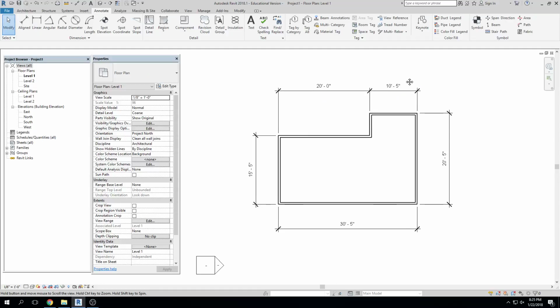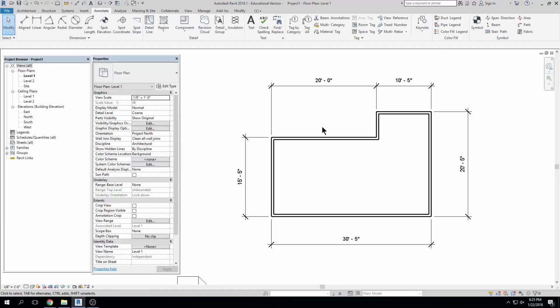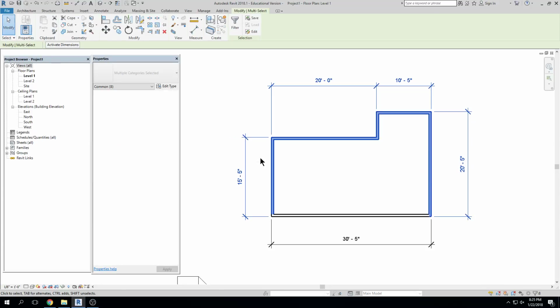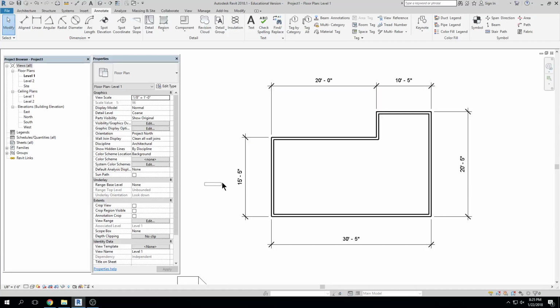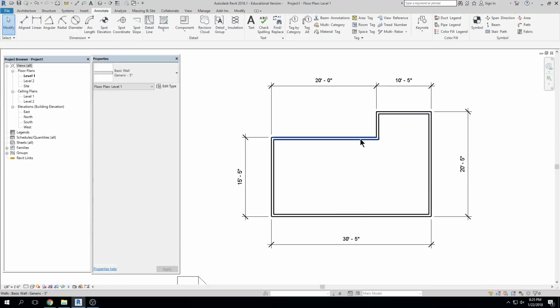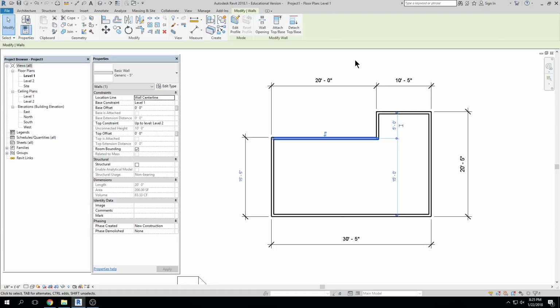All right. So move is pretty easy, right? I could also grab more than one object. So when I'm selecting things in Revit, I can do a selection window from the top right down to the bottom left. Anything I touch gets selected, right? I can click from the bottom left to the top right, and anything that is encompassed in that selection set is selected. I can hit escape. I can pick, click. I can hold down control, click, click, and I can add to my selection set.